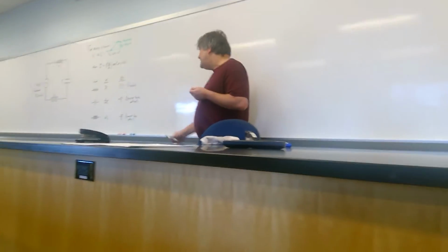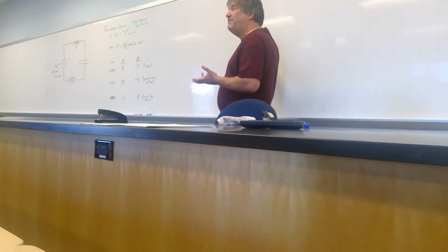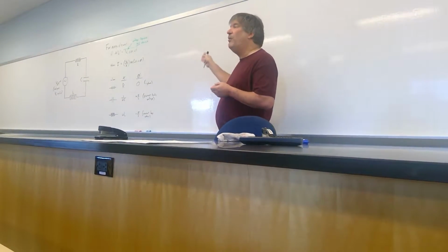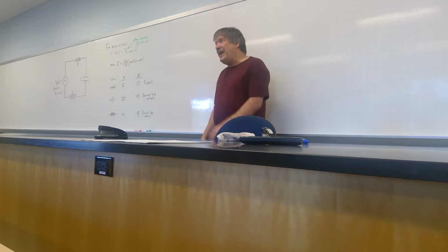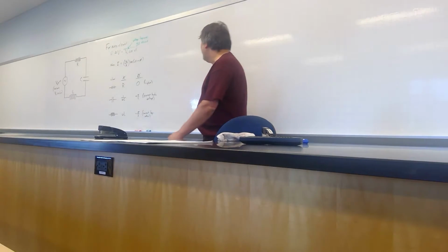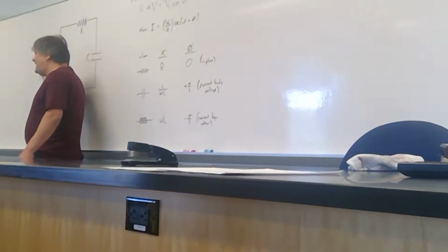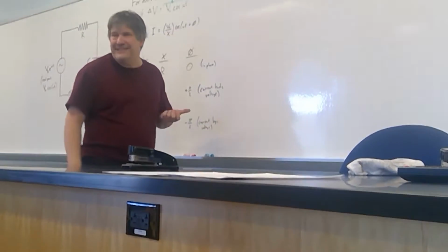And I'm going to use that technique that we did last time of plotting out phasors, rotating phasors in the complex plane, to actually figure out what the solution of the differential equation is. There's a second way that I want to show you how to figure out the solution, which is relying on that wonderful little Euler equation, the e to the i omega t, that you can substitute in anytime you're going to use a sine or a cosine.